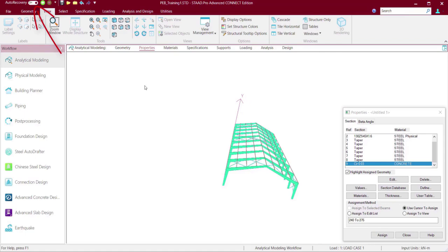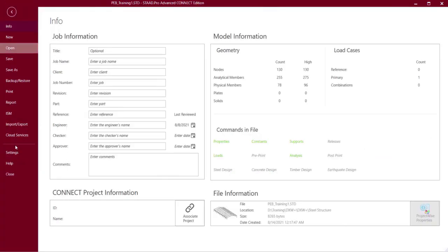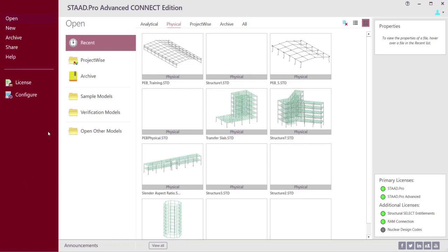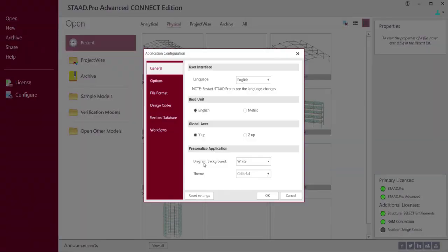Or if you think manual saving is risky because someone might forget to save frequently, then you can make sure that your autosave option is properly set. You can access this configuration: go to the startup page, go to configure, go to options. Now you can see here there are some options like save, auto recovery information and so on.